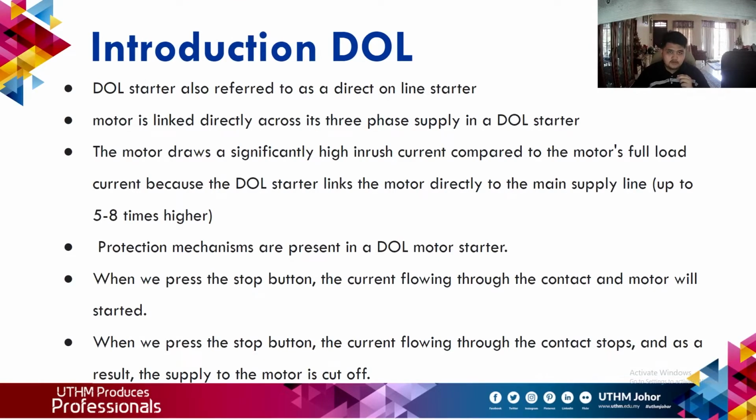So, introduction to DOL. DOL, also known as a direct online starter, means the motor is linked directly across its three-phase supply. In a DOL starter, the motor draws a significantly high inrush current compared to the motor full load current, because the DOL starter links the motor directly to the main supply line, which is usually 5 to 8 times higher.